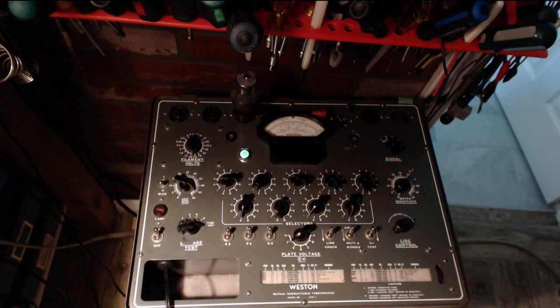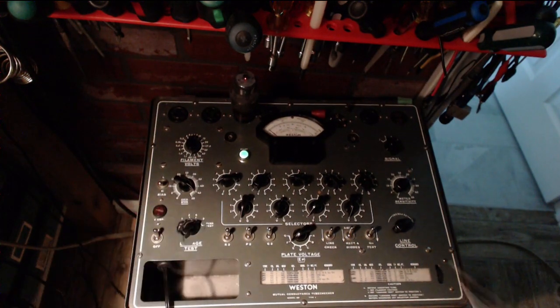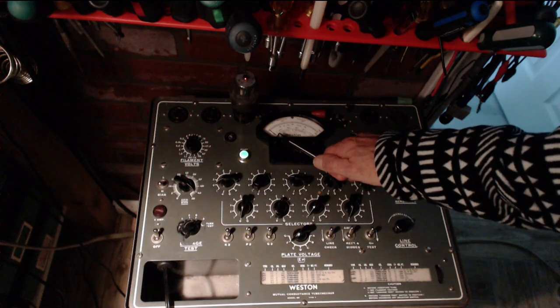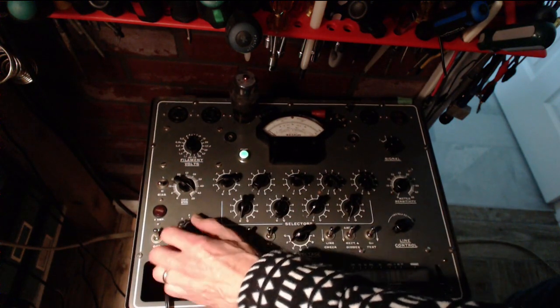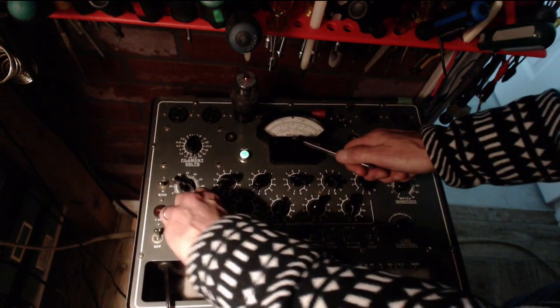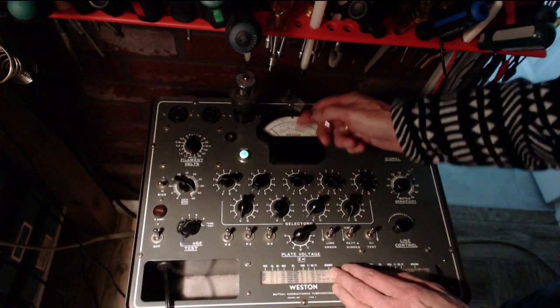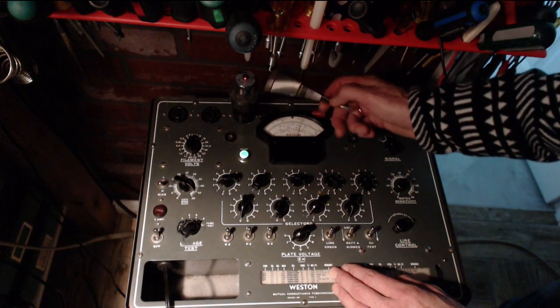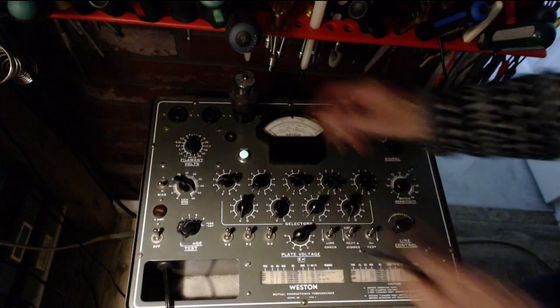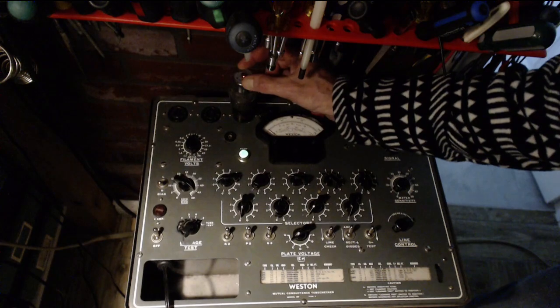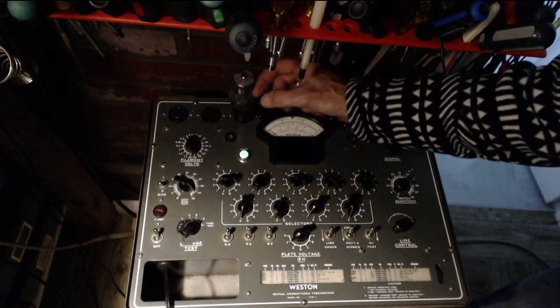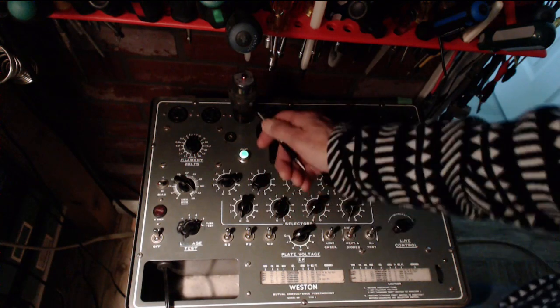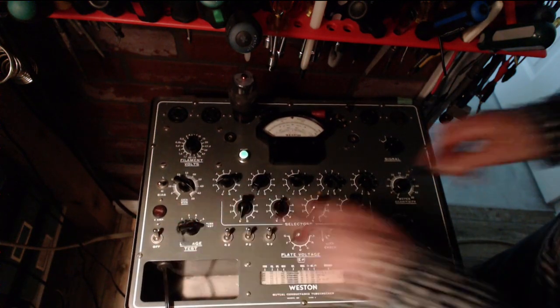Well, I wasn't going to record any of the tube testing because I tested these tubes before, but as soon as I went to do the short test on this tube, to position number 5, so that's up a little bit. That's not its normal spot. That's more normal. And the first time I did this was much higher. Wonder which tube is noisy? Now, is that a socket problem? I don't think so. Better not put this tube back in with a short in it.